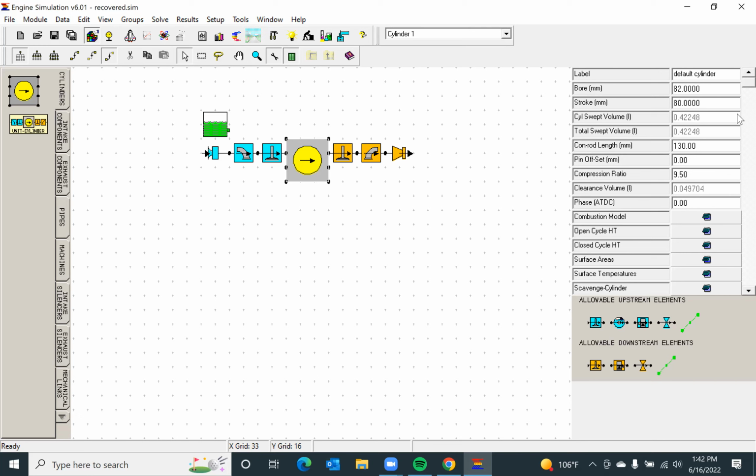Then clearly the next question is, are you using a diesel engine or a gasoline engine? A gasoline engine would have a low compression ratio, typically between 9.5 to 10.5. The diesel engines would have a higher compression ratio, 19 to 21. So since we are going to use gasoline, we are going to use the compression ratio for gasoline.